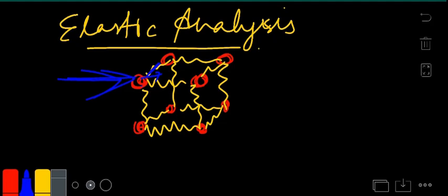Okay, so in this particular range, we can understand that there is no plastic deformation. We'll be talking about it later, but understand it now: the balls that have been subjected to a certain force and displaced from their original position come back to their original position. So it does not deform permanently. When a material does not deform permanently, we might say that the structure is behaving in its elastic range. It has not gone to its plastic range. It is behaving in its elastic range.